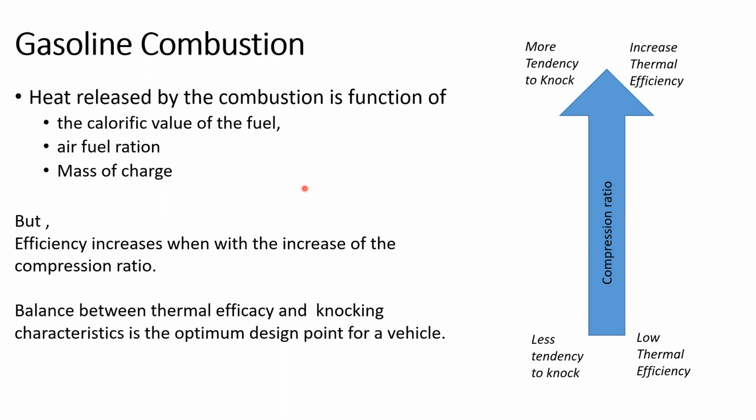Once the intake valve is open and the piston is moving down, the air is sucked in by the lower pressure inside the combustion chamber, inside the cylinder. That's how we usually get the air. This process, where air comes into the combustion chamber just by the pressure difference between the atmosphere and the inside of the cylinder, is known as naturally aspirated engines. It draws air from the outside because of the pressure difference.